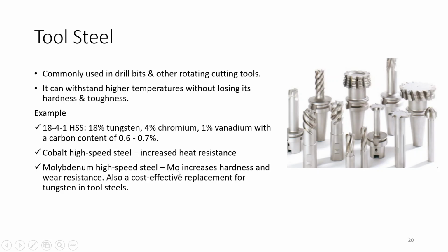So substitutional type of solid solution will be there, and also carbides will form. If you are forming, for example, vanadium carbide or tungsten carbide, these carbides are ceramic elements, right? So they will act as a barrier for dislocation movement. They will again provide dispersion type of strengthening. So, solid solution strengthening as well as dispersion strengthening.